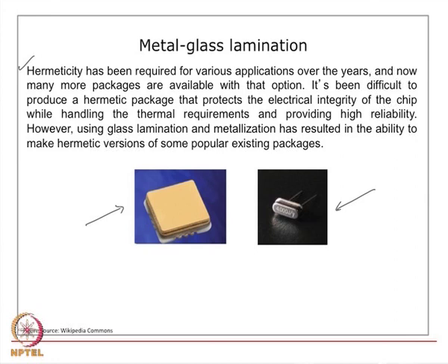But in hermetic sealing, this is not allowed. The die and the first level interconnects are completely sealed, checked for airtight sealing after the process is over, and it definitely could be expensive compared to the normal plastic encapsulation or a ceramic encapsulation.